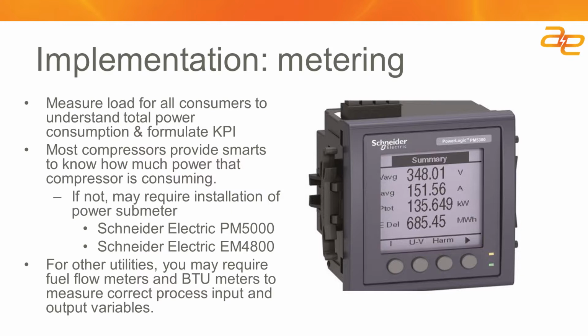But all of these, in order to implement an equipment sequencing control scheme, require that the various input and output parameters be measured in real time, because your control scheme, whether through your programmable logic controller or your DDC system, is going to have to make decisions on which machines to sequence on and off based on real-time measurements coming from not only installed instruments but calibrated equipment.